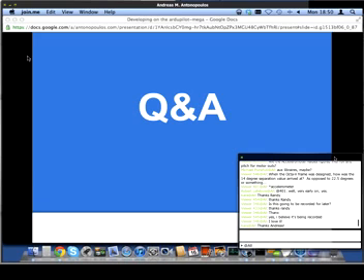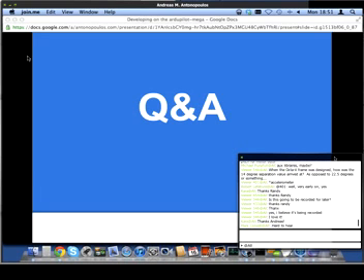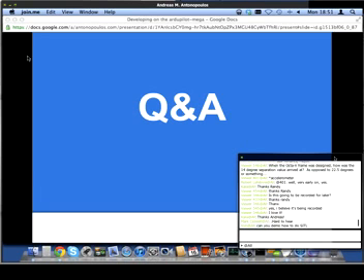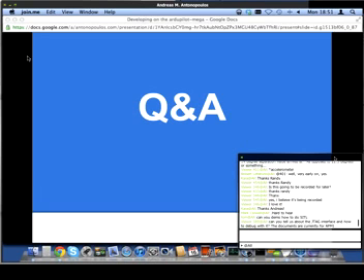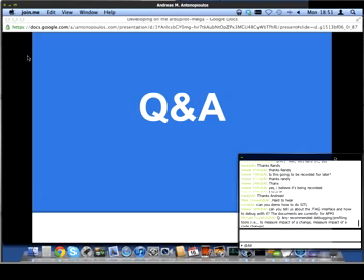Yes. So I see that we are using the A to D interface of the sonar. I believe it also has a serial interface. I'm not sure. The sonar, I believe, uses an A to D controller on APM1 and APM2. Wouldn't it be more accurate if we use the serial interface, where we get the exact number of bits as to what the height is?